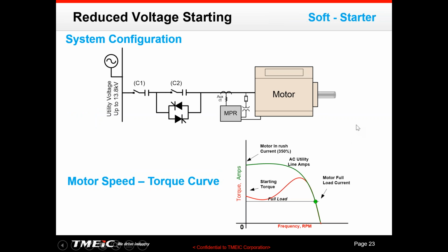Now, the soft starter, this is the main one we use these days. If you cannot start the motor on the DOL, then we use a soft starter. We use the soft starter, with power semiconductors, to start the motor. And once again, then we bypass and the motor runs at the DOL.